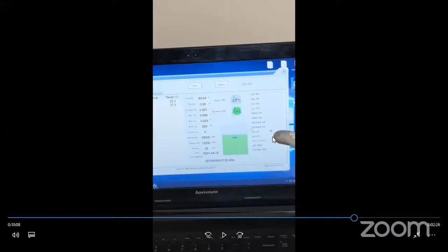This is how, when you leave your electric vehicle connected to the charger overnight, or maybe there is an inrush current passing from your switchboards or from a household power supply, if your BMS is configured properly and has all the protection level circuits, no matter what, even if you charge overnight or there's a sudden inrush current via the power supply, it's the BMS's role and responsibility to cut off and protect the complete battery pack, even from the charger.